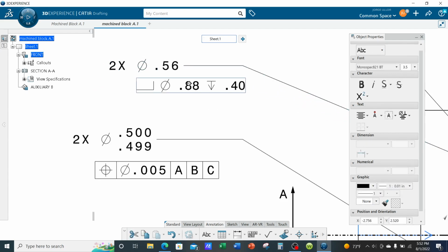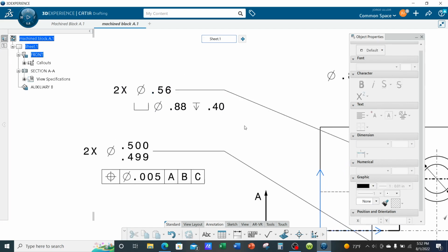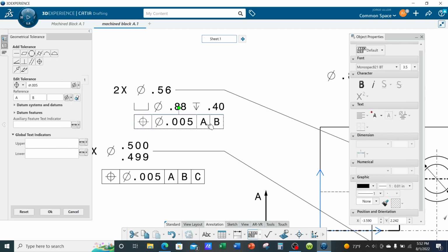And let's add a tolerance. We're going to go with the very loose tolerance on this one. Get to practice applying GD&T. So we'll do a positional tolerance of, let's go 28 thou, 0.028 with respect to datums A, B, and C. And OK.